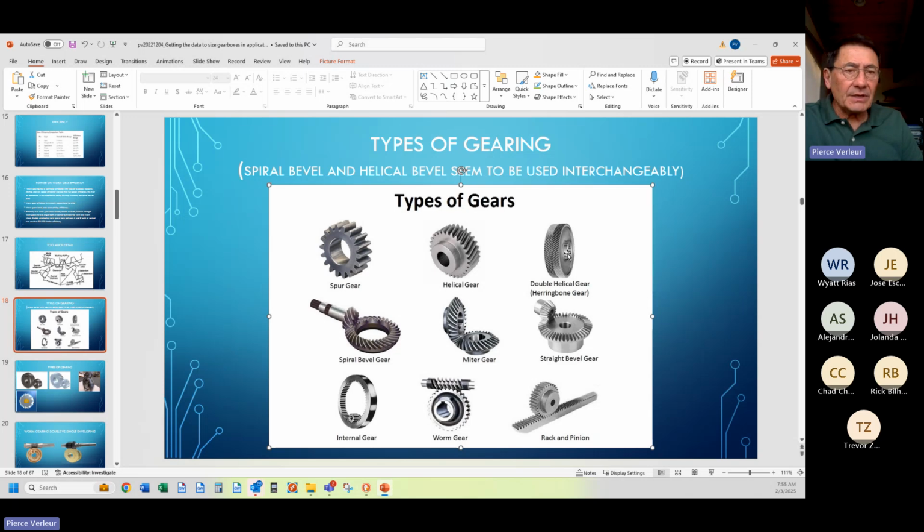When you want to turn the 90-degree corner, you go to a right angle technology, which would be this, this, this, and the worm gear. This gear here is a pinion on a bull gear. This one's internally toothed. You can have externally toothed as well. That's also still a linear technology. Very common here, by the way, on turntables and slewing drives. This is a rack and pinion. It's for linear motion. It's turning rotary motion into linear motion.